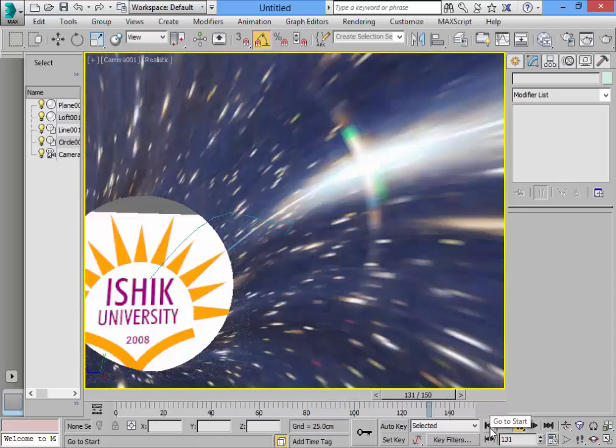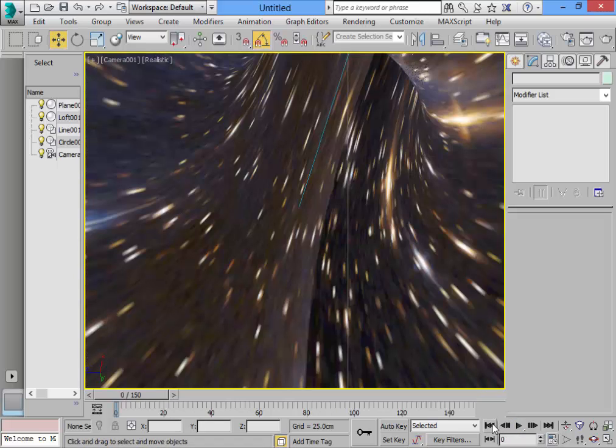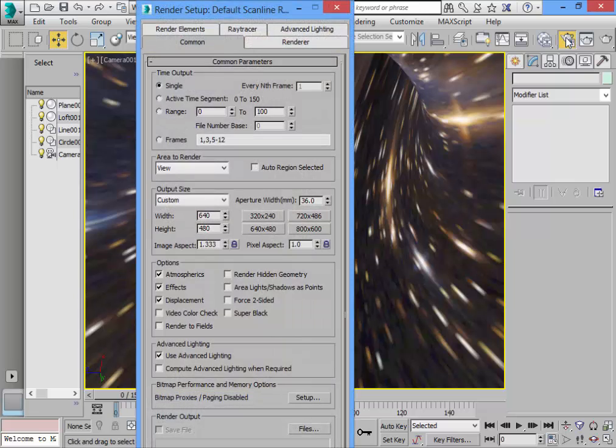Now, if you are happy with this sort of practice and if you want to render it as video, because from now on we are not going to render just the pictures, we are going to render videos. To render a video, you need to click on this render setup. From the render setup, you will not render only a single frame. You will render all the active time segments from the start till the end. And because we don't have time to render it in a perfect way, I'm just going to render it in a small dimension. It is 320 by 240.